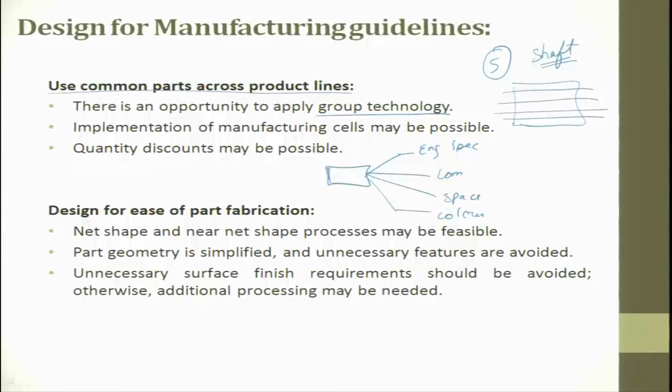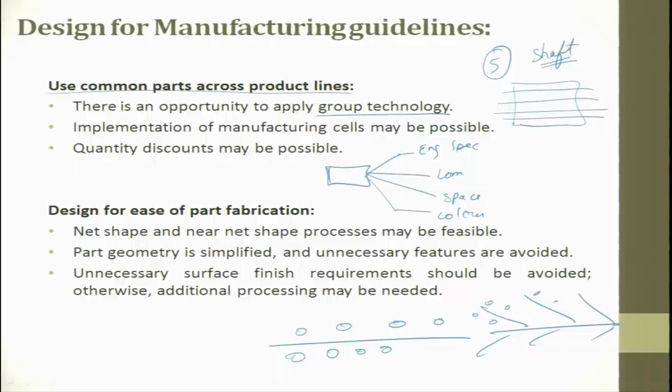This we have gone one step deeper into. When you apply group technology, I can start grouping the machines, and each group I call a cell, so I can have more number of cells. The idea is, rather than having a single conveyor and so many machines around, I do clustering. I have individual lines, maybe all trying to produce the same part, and several lines go in parallel and produce the output which comes to the main conveyor.